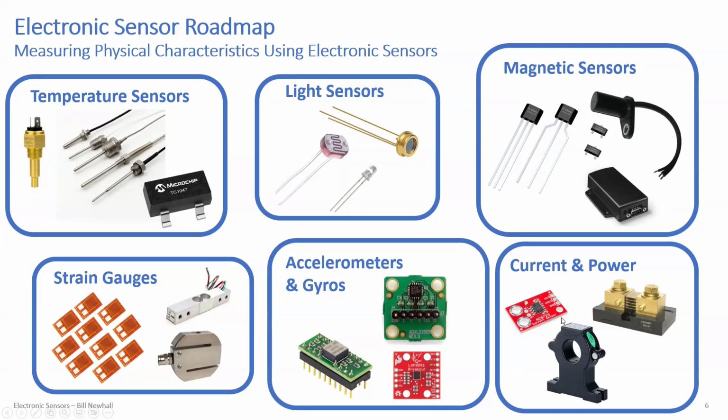All right, imagine if you had a current sensor on your project right now to figure out the voltage delivered to the motor, right? You know the duty cycle of a pulsed voltage. If you knew the current, then you could figure out how much electrical power is delivered to that motor and get a good measure of how much mechanical power is being delivered to the air, really, to push the aircraft forward if that were an aircraft.